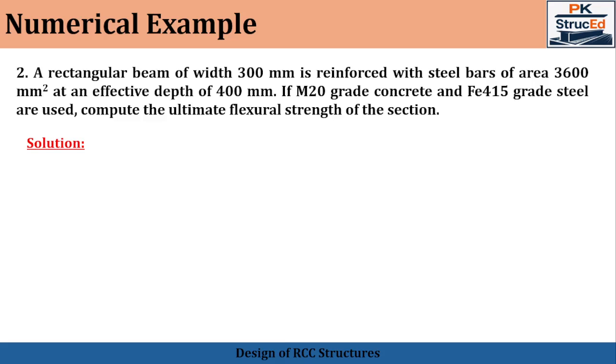So again, similar to the previous problem, we should calculate the actual depth of neutral axis factor, and that should be compared with the maximum depth of neutral axis factor. Based on that, we can define whether the section is under reinforced or over reinforced, and finally the moment of resistance or the ultimate flexural strength of the section can be computed.